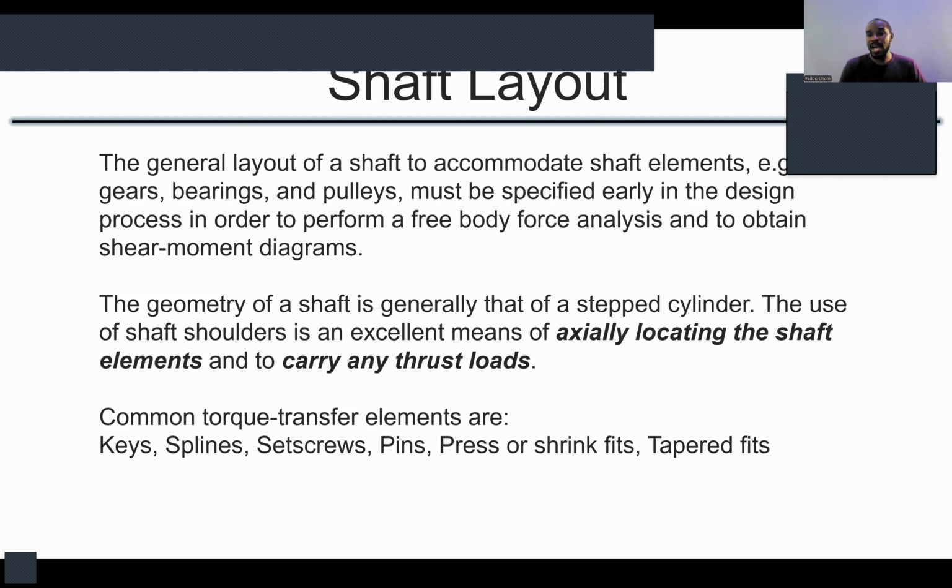All right. And we need that shaft layout when we come to our calculations, because we will need to do bending moment diagrams and force diagrams. Those values, we pick the maximum of those values and put in equations to calculate. So your free body diagram is needed. You must know your shaft layout. Where exactly are you fixing your gears or pulleys? Where exactly are you fixing your bearings, as the case may be?